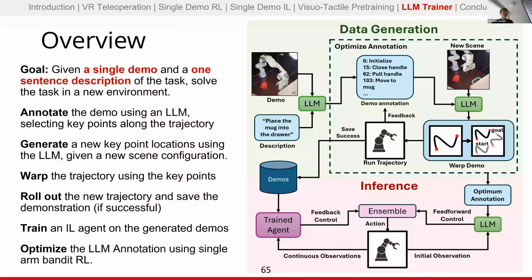But that answers the second half of your question, what are the limitations of this method? The main limitation is, one, the task has to be solvable by the LLM. So there is just a level of task understanding. The LLM is really good at that from a semantic standpoint, but sometimes the physical understanding fails. For example, if we have tasks with a lot of rotation, that rotation information is just hard for the LLM to understand very well. Or if you have super precise tasks, that could also run into issues. Now in simulation, I wouldn't be so worried, because the LLM is very good at going, oh, hey, we start off 2 centimeters to the left, and then we want the object to be changed, so therefore I just add this exact value.